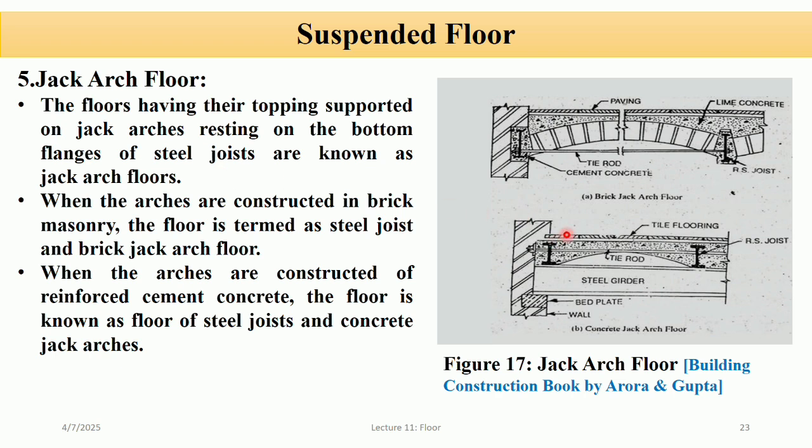So steel joists are placed parallel. You can see in this figure, this is the steel joist, and the jack arch spans the gap between the bottom flanges of these joists. So the topping is laid above the arches to complete the floor.